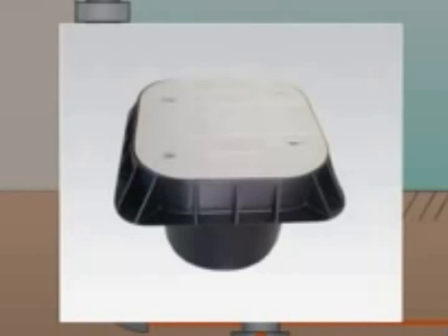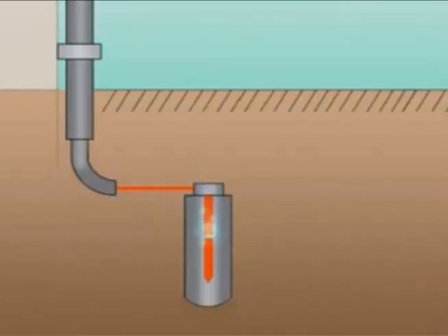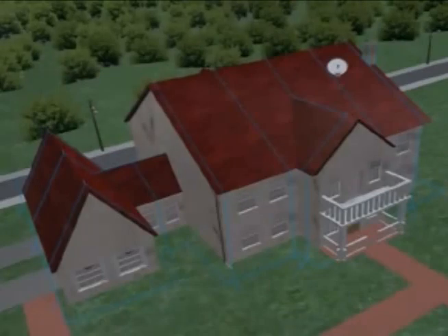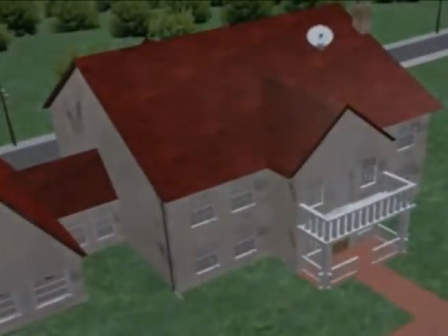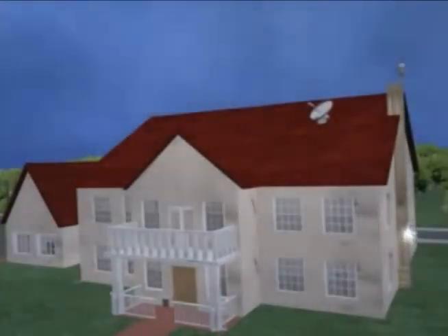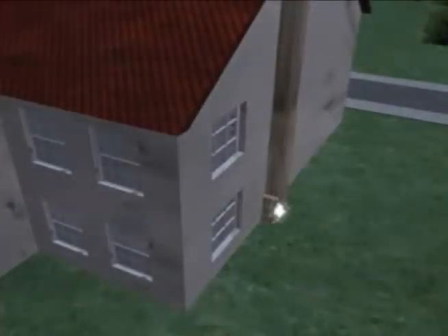The arrestor assumes the same nature of charges as the earth. Negative charges are attracted to the points and conducted to the earth. In case lightning occurs, the arrestor provides a path for the remaining charges to flow to the ground, thus protecting the building.